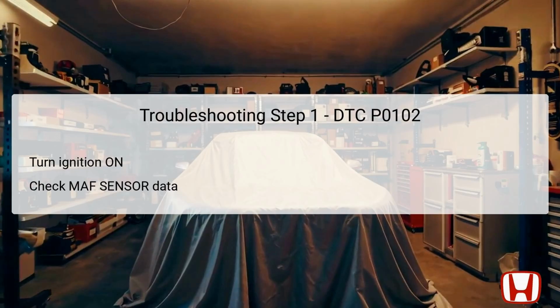If the reading indicates approximately 0 grams per second, G/second, or a voltage of 0.1 volts or less, this confirms the failure in the system. In such a case, you would proceed directly to the second troubleshooting step. Alternatively, if the readings do not show these low values, it may indicate an intermittent failure. This could lead you to inspect for poor connections or loose terminals at both the MAF sensor/IAT sensor and the ECM.